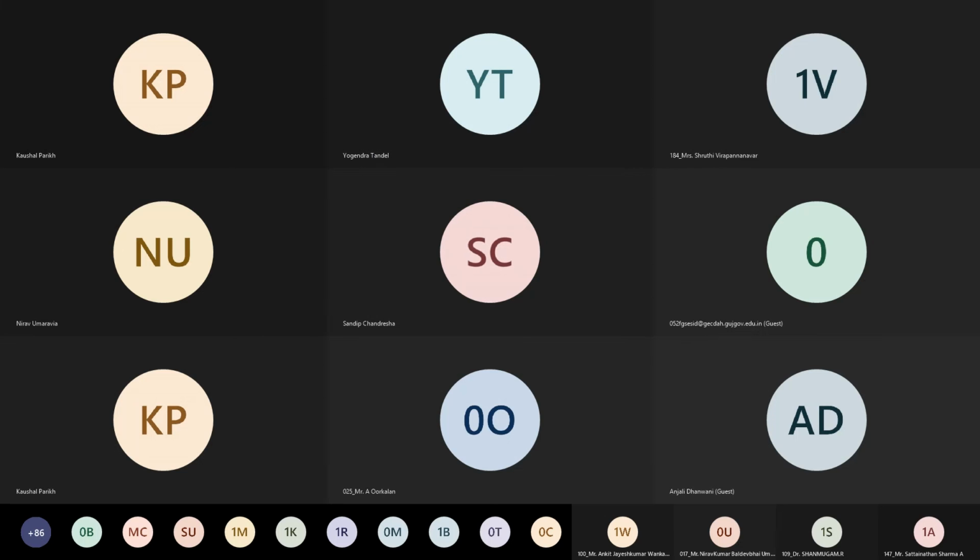The grouting material is used for gap filling or to increase the strength and durability also. Grouting can be used, first, maybe as gap filling, yes, definitely. In certain cases, grouting doesn't increase the strength by itself, but a good bond will increase the strength. So definitely it will increase the strength if there is a good bond.